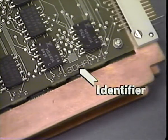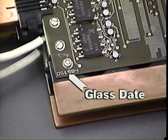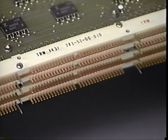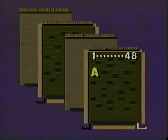Each circuit board has its own identifier and its own glass date. Each board has a connector with 48 pin pairs. These pin pairs are for the true and false output and input terms. On board A, the pin pairs are numbered 1 through 48. On board B, the pin pairs are numbered 49 through 96. On the C board, the pin pairs are numbered 101 through 148. On the D board, they are numbered 149 through 196.